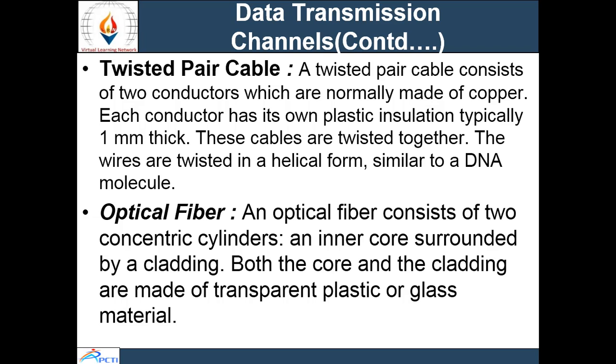Optical fiber use reflections to guide light through a channel. The density of the core and cladding must differ sufficiently to reflect the beam of light instead of refracting. The core is used for guiding a light beam, whereas the cladding acts as a reflector to prevent the light